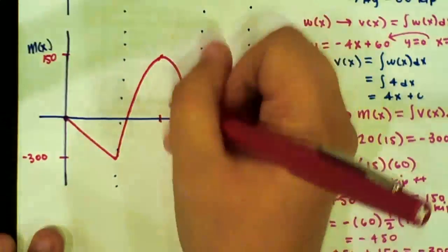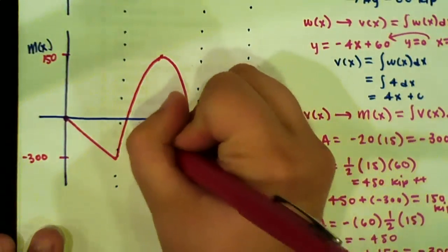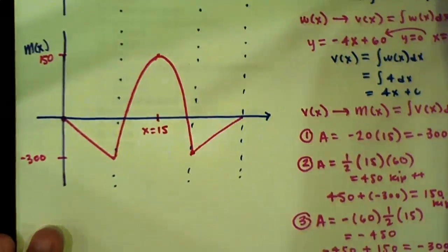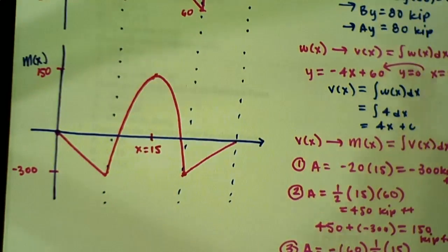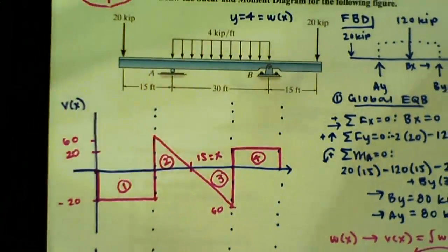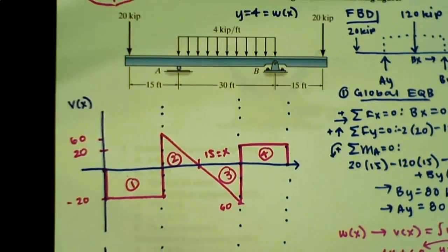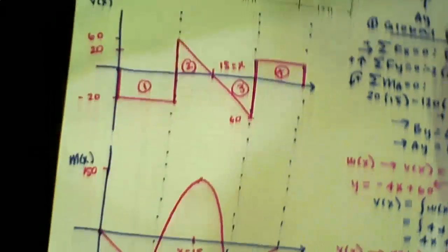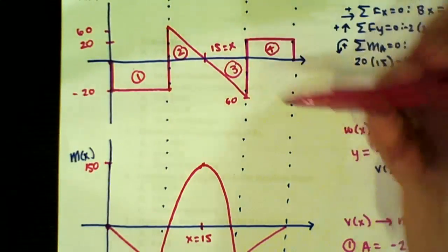And we found that our maximum takes place whenever x equals 15. Because of the first derivative test, you find where the derivative is equal to 0, and that's where its maximum or minimum starts. So inherently, if you see the shear cross over the x-axis at a point that isn't a break point, you know that there's going to be a maximum or minimum there.